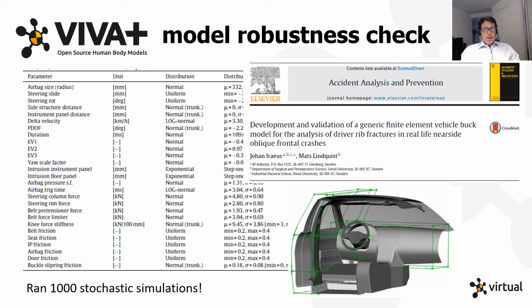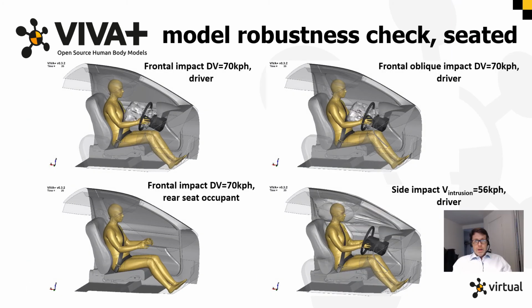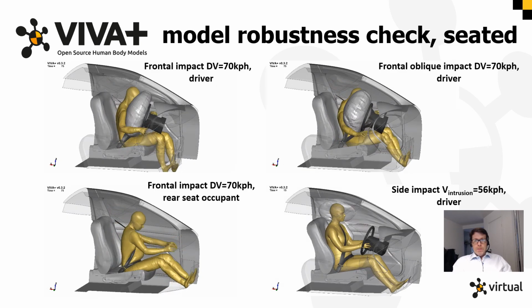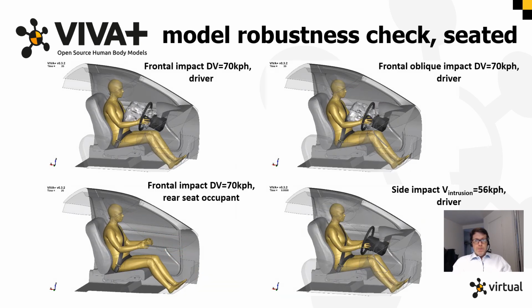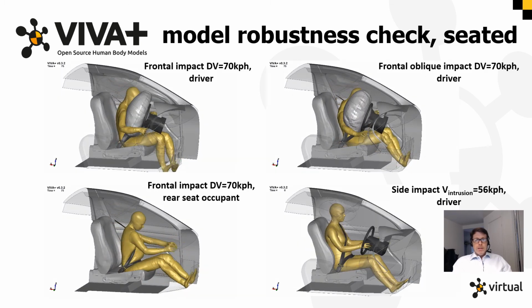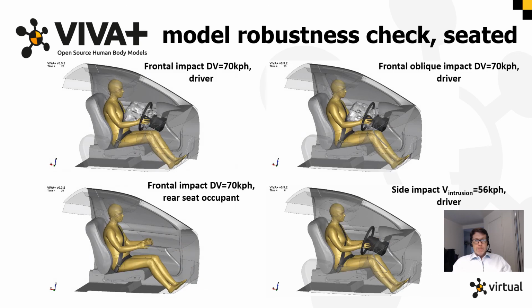After the first iteration, I had many error terminations. Then, compiling the root cause of all these terminations, I discovered that we had a few problematic areas in the model. I did some updates, and after a couple of iterations, I had a model that was much more robust. Based on this, we created a small subset of severe impacts, exercising different parts of the model. We always run these robustness load cases after each model update.